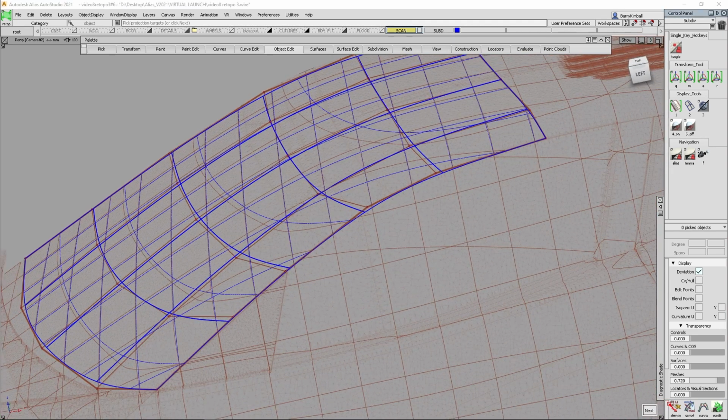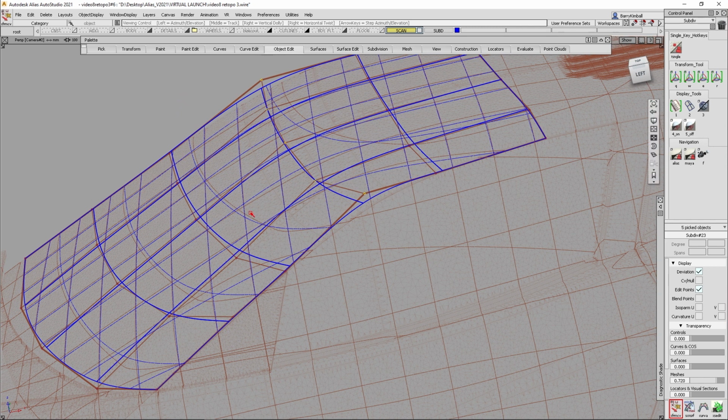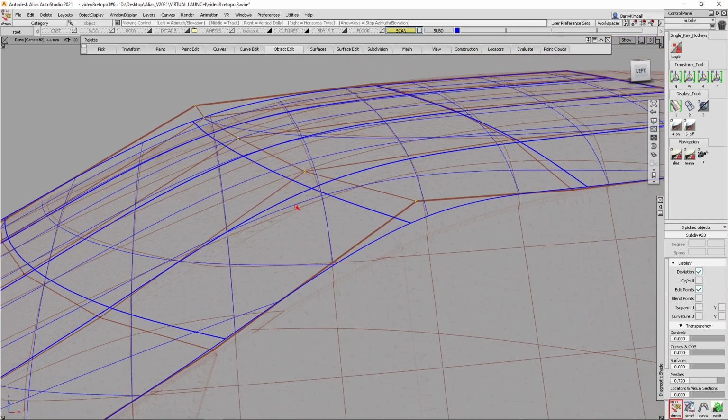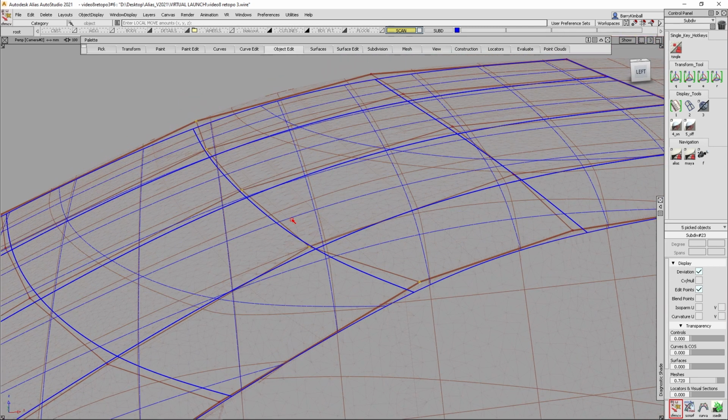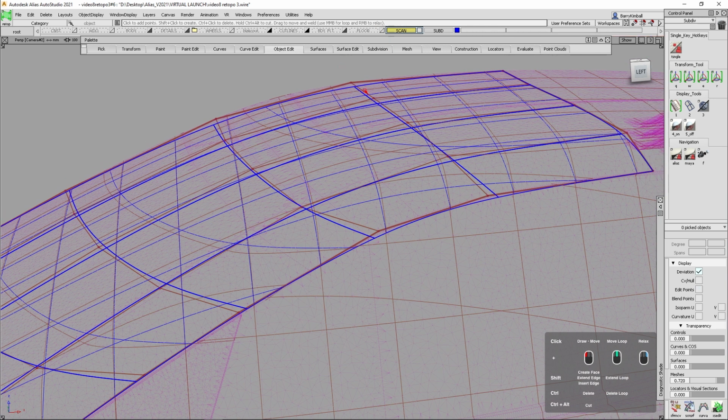So if I go to something like a Move CV tool and I grab a row, I'm free to move that row off of the reference data, okay? I'm just going to Control Z that and show you a next option. If I query edit this tool and I bring up the options for the retopology tool, I could turn persistent projection on.